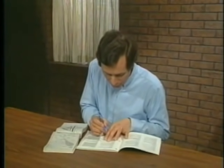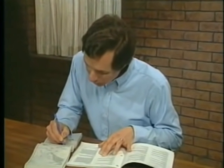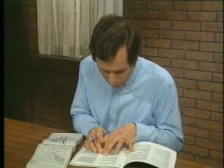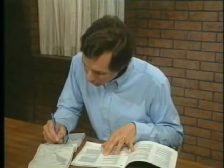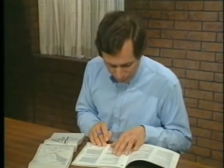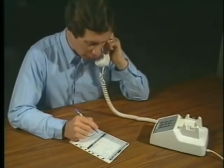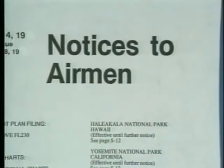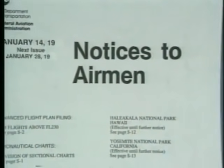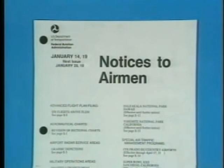FDC NOTAMs are issued to amend instrument approach procedures and aeronautical charts. It is extremely important to check these prior to an IFR flight and update your flight information where necessary. During your pre-flight weather briefing, you should make sure you receive the latest NOTAMs for your flight. NOTAMs printed in the Notices to Airmen publication are not normally included in the briefing. Therefore, you should always check this publication during your pre-flight planning.